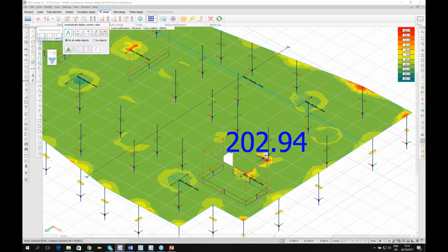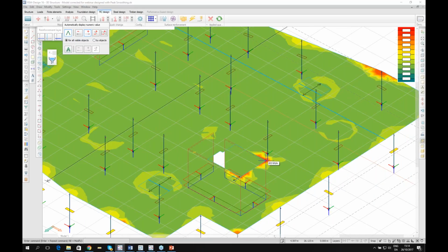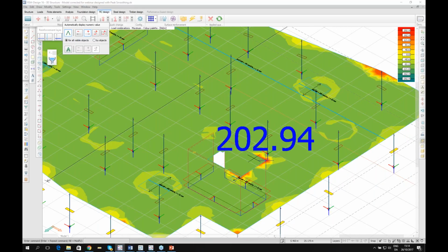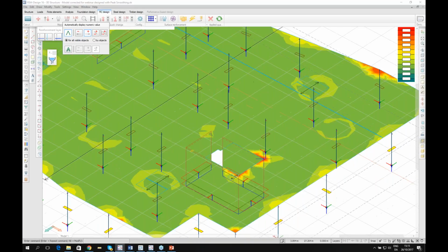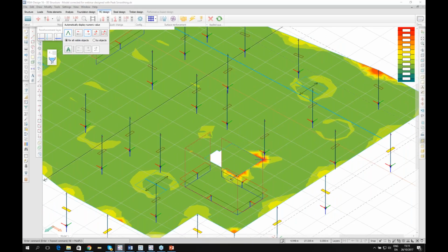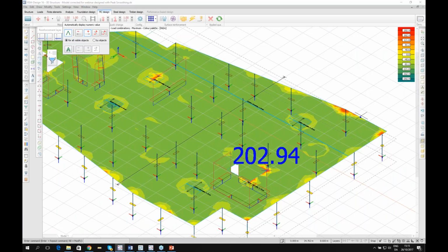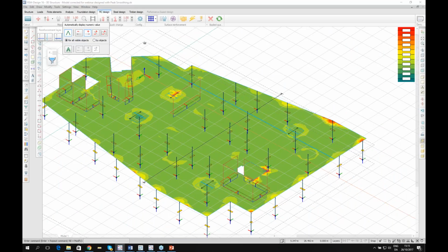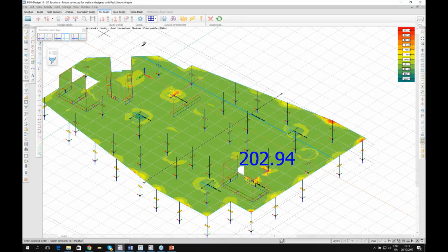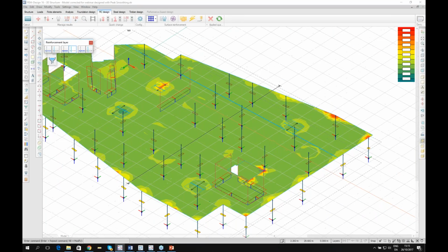This is something that you have to do on your own, but some shear reinforcement is needed here around the walls, and some stirrups can be added here. Also at the edge of my plate and here. But I can see the missing shear capacity on my plate.